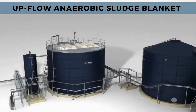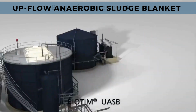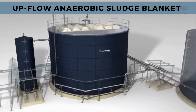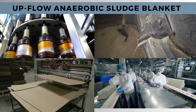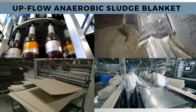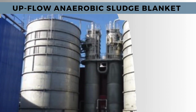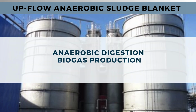Upflow anaerobic sludge blanket reactors are used for industrial wastewater treatment. They are commonly used in industries like beer, sugar mills, pulp and paper, distilleries, and food processing. Key processes of the upflow anaerobic sludge blanket are anaerobic digestion and biogas production.